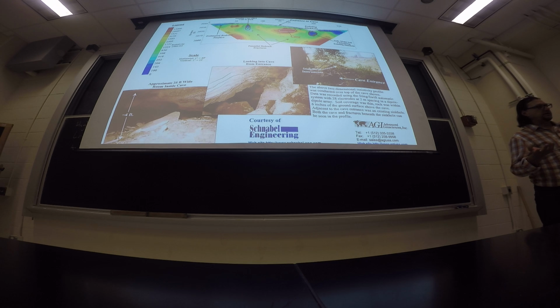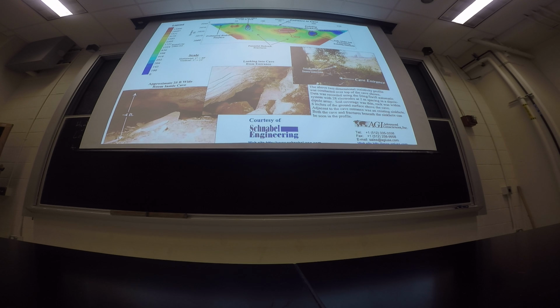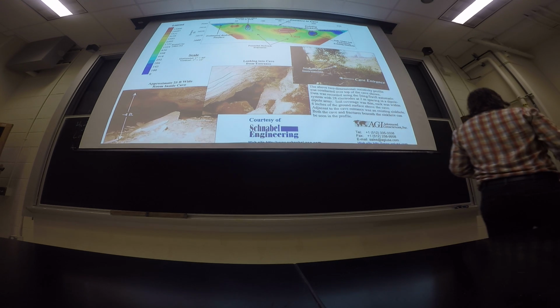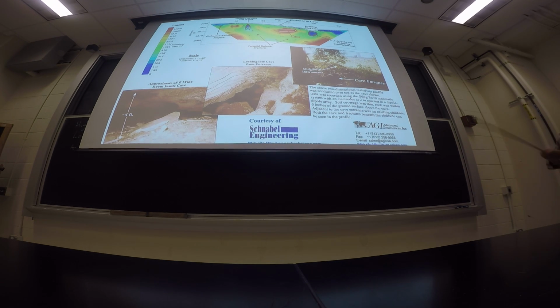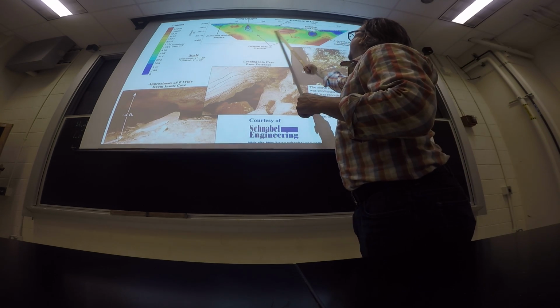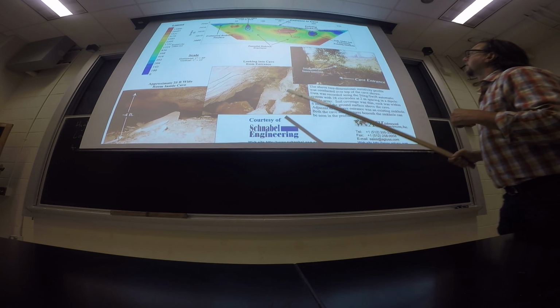You can look for higher resistivity, because the rock, the limestone, even though it's low porosity, does generally at the near surface contain some porosity. It'll be that porosity if it's below the water table, or it'll be partially saturated at least. So you'll have a lower resistivity than an air-filled cave void would be. This is just an example where they did a resistivity survey across an area, and they noticed in this location right here a very, very high resistivity anomaly.